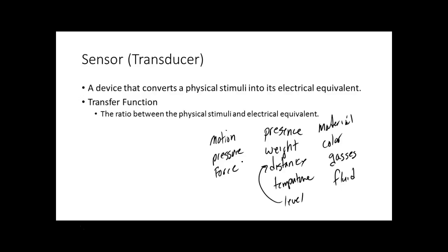So my car weighs 2,000 pounds. It don't weigh 30 psi. You understand that? So pressure is something that creates a force. Force, which is something that will cause a device to tend to or change directions, is equal to area times pressure. So we can't have force unless we have a what? Pressure. So pressure is a push, right? Or it's a difference in potential. If we got pressure, then we can have a force, but we're going to have to push that against a what? An area. So pressure is the actual push that causes the direction change, but the pressure's got to push against something. If we don't push against something, then we don't have what? Force. So we have force sensors, we have pressure sensors. They're two different things, right?